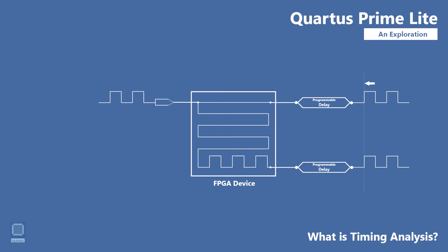Timing analysis is in fact one of the final verification methods, but since it is so critical to FPGA development, Intel has decided to include this warning at an early stage to notify us, the developers, to incorporate the timing constraints from early on, so that in a later stage we will have mitigated most of the delays and have an easier time finishing up with timing analysis for verification.